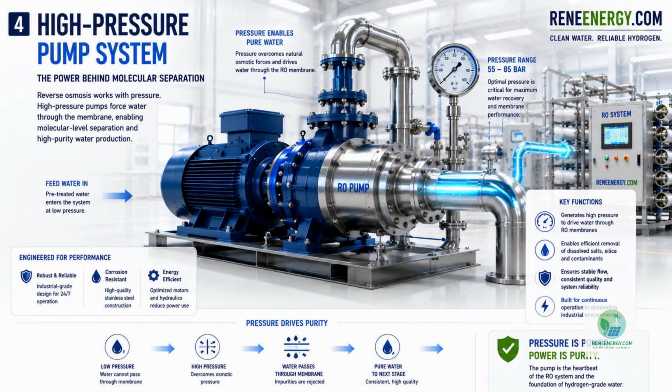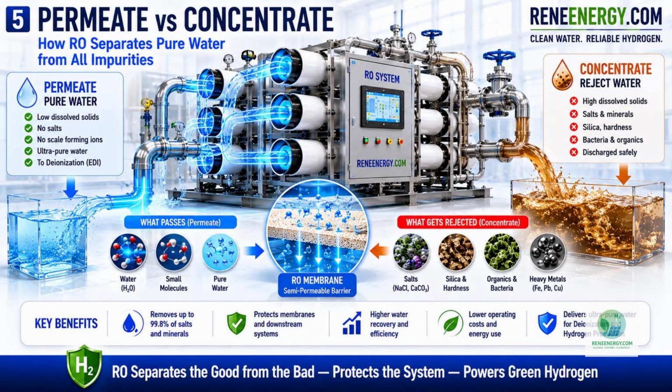This is where engineering economics enter the story. Every extra unit of pressure costs energy, but insufficient pressure risks poor purity. The RO pump is therefore not just a mechanical device. It is a control point for performance, reliability, and operating cost. Image 5 explains permeate versus concentrate.